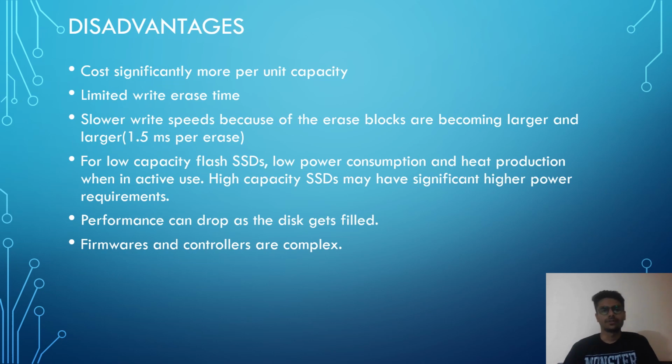Disadvantages: cost significantly more per unit capacity, limited write erase times, slower write speeds because the erase blocks are becoming larger and larger, 1.5 ms per erase. Low capacity flash SSDs have low power consumption and heat production when in active use. High capacity SSDs may have significantly high power requirements. Performance can drop as the disk gets filled. Firmware and controllers are complex.